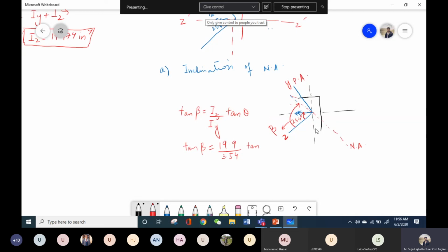And these sign conventions are based on the conditions that we considered for the derivation of formulas. So for every formula, there is one figure on which we have shown our positive. If that is the case, then we will use the positive symbol. If not, then we have to use the negative symbol. So you cannot apply that condition that counterclockwise is positive in this one. You have to consider its own figure and its own sign convention. Did you get my point?